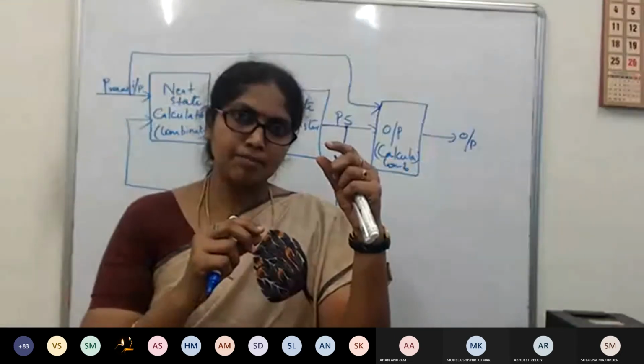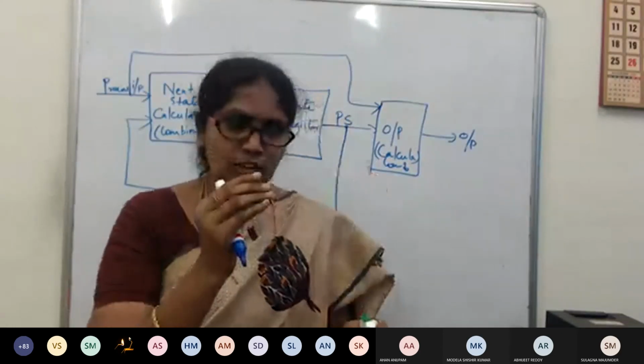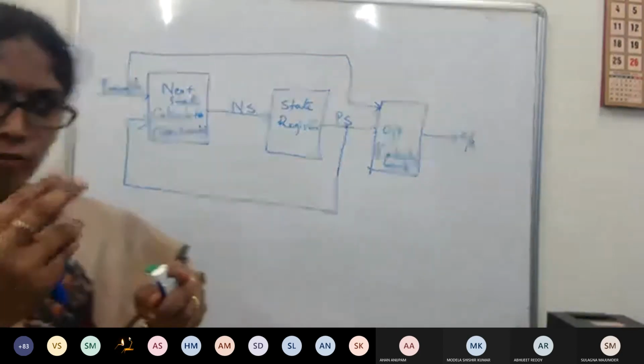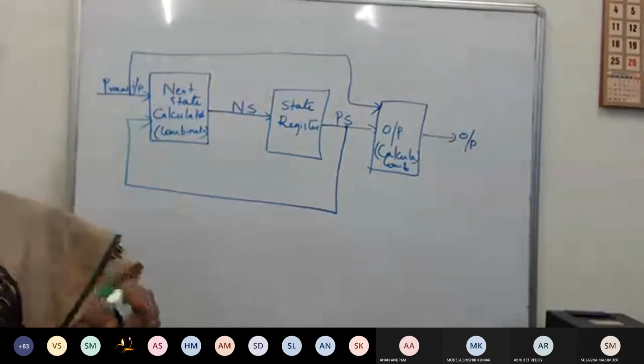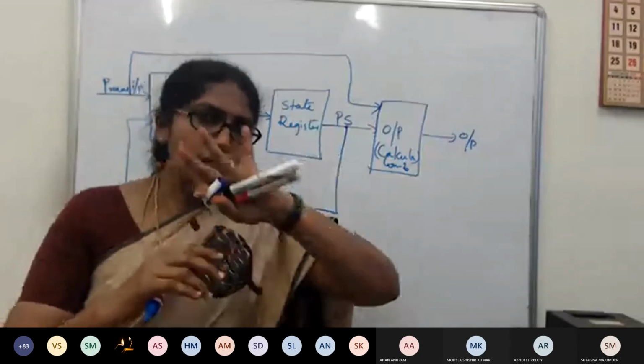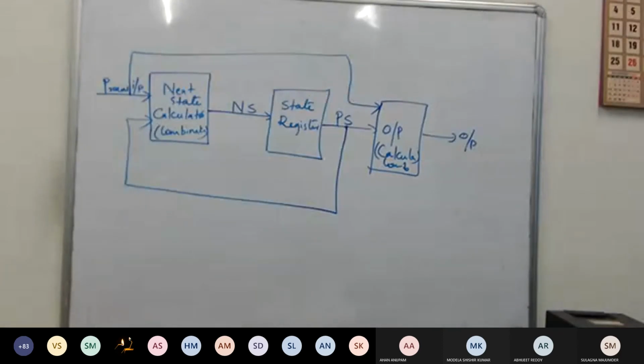First, one bit will come. Only a single bit has entered the machine, so it cannot decide anything, because it is detecting a minimum 2-bit or 3-bit sequence. If 3 bits are detected, all 3 bits have to enter before a verdict is given. Bit by bit it enters, and 3 bits have to come, otherwise it will not decide. Yes or not? Yes, ma'am.